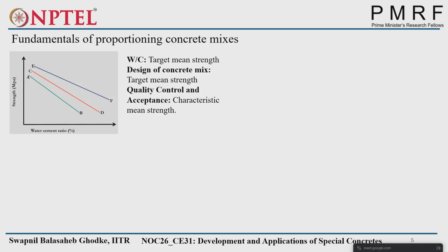Okay. So it depends upon the hydration mechanism internally. It's not always the case that some cement remains unhydrated. Sometimes it remains and sometimes it doesn't. It depends on the hydration reaction inside the concrete. So, to keep the extra water from evaporating, we are going for curing also. Whatever water is available in the concrete or the cube will hydrate the remaining unhydrated cement.